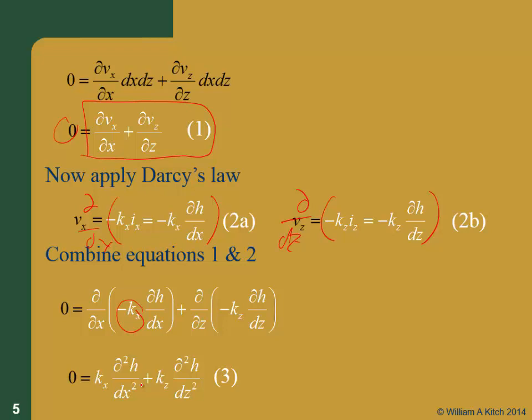And what two laws have I applied? I want to use two things here. Continuity and Darcy's law. So the assumptions are that I have a saturated material, the volume's not changing. So this doesn't work for a soil that's swelling. It doesn't work for a partially saturated soil, but it works for a saturated soil where there's no volume change.